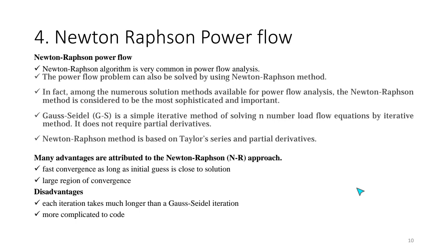They also use the Newton-Raphson method, and a few of the softwares you are already aware of, for example PowerSimulator, SimScale, DIgSILENT PowerFactory. And there are other softwares available in the market, which we're not going to use as part of the course, but for your knowledge, it could be the ETAP platform, the RSCAD platform or PSCAD software. Those are also available in the market, and also use the Newton-Raphson power flow method.